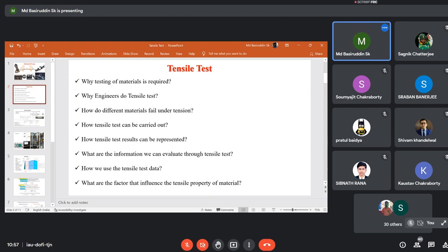Now the question is what sort of specimens you will fabricate. First you need to know that. So what sort of specimens do you need to fabricate? First give me that answer. A dog bone shaped material. How do you know? Because the specimen must be held securely within the jaws of the testing machine, so we need an arrangement for that. Okay, I agree with your answer.